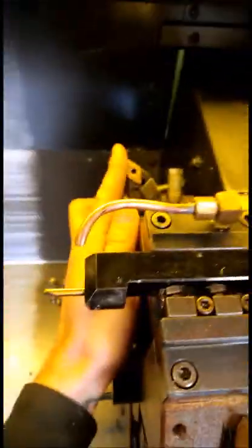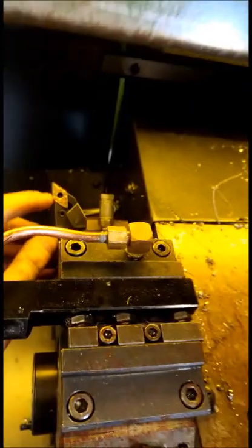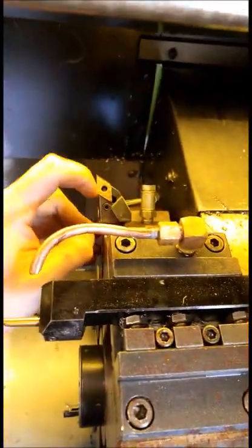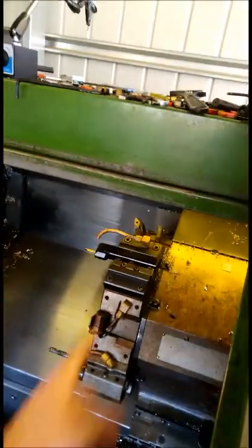The angle there, the cutting angle, so that's this face here, and then that angle there, 55, is the included angle of the point, so around there, and it needs all of this info so it can work out what kind of angle it can put on a back face of something. Width 20, so that's just the width of the shank.